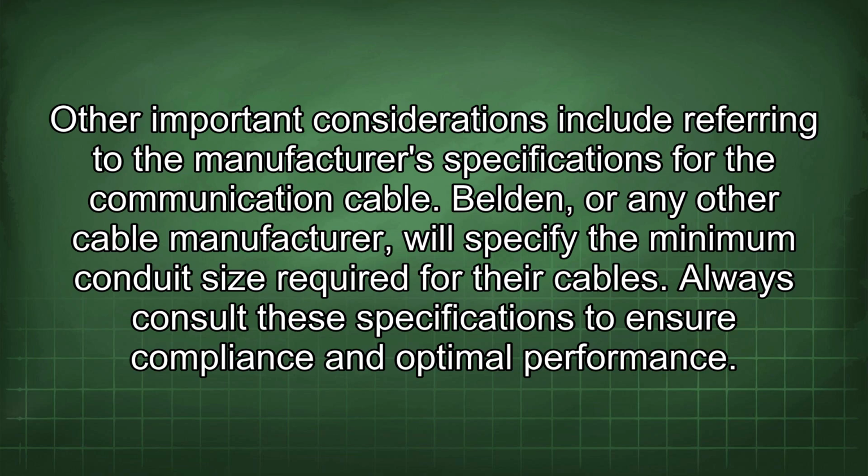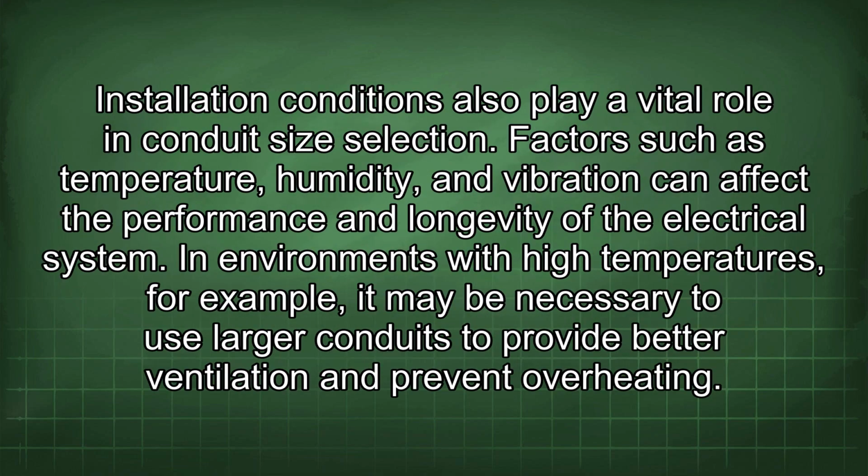Belden, or any other cable manufacturer, will specify the minimum conduit size required for their cables. Always consult these specifications to ensure compliance and optimal performance. Installation conditions also play a vital role in conduit size selection. Factors such as temperature, humidity, and vibration can affect the performance and longevity of the electrical system.